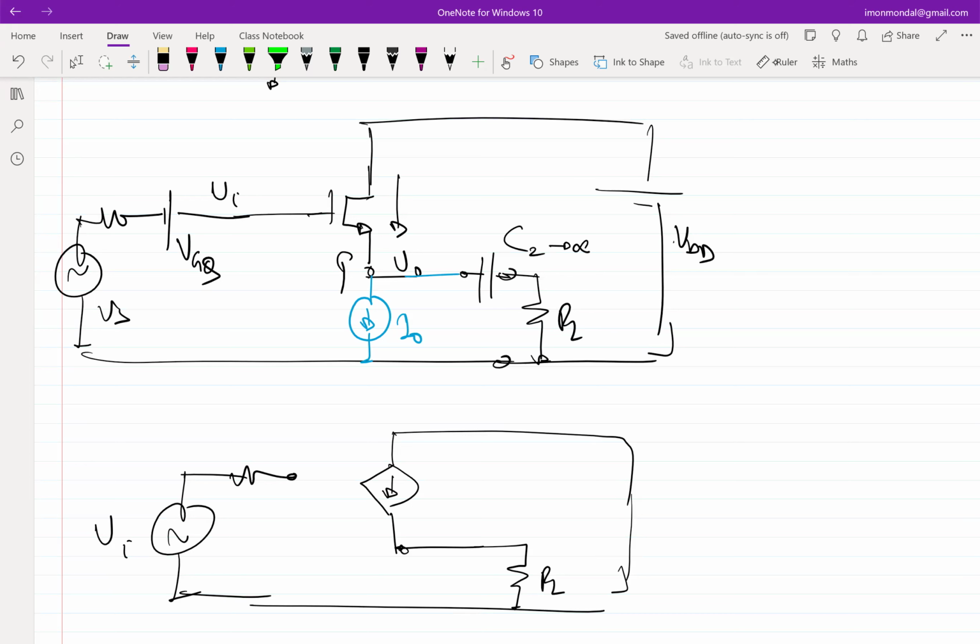Any questions? Okay. The previous approach will also work, but there are certain limitations, and the limitation was this. If I use this, then you have to make R naught much greater than RL. That is one piece, right? In the quiescent picture, all the incremental current is flowing into R naught, so if you make R naught much greater than RL, that voltage is likely to increase.